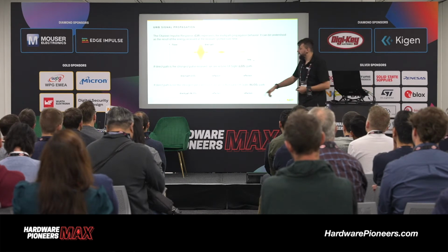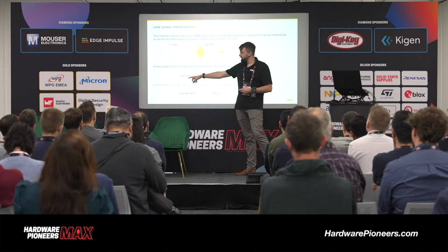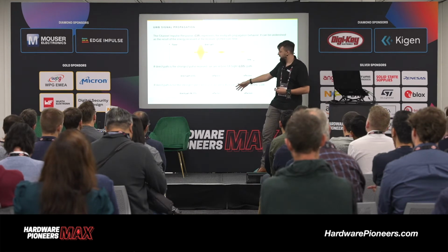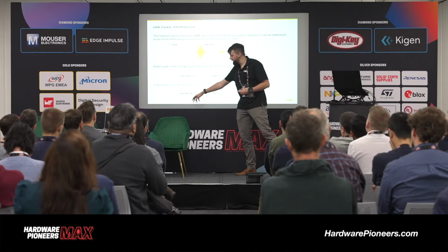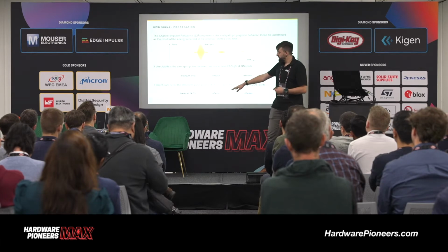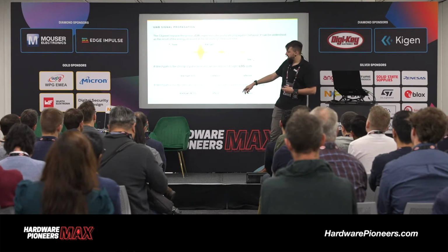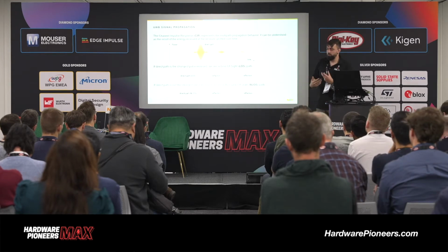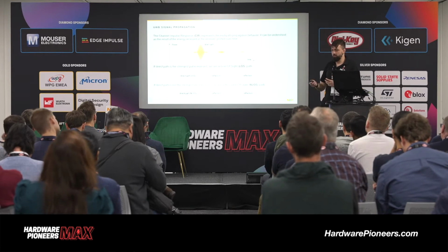You can see here, if we have a line of sight condition, the direct path is the strongest signal, and then reflections come in afterwards. In a non-line of sight condition, we have the direct path, which is not the strongest, but it's still received. And we have the first reflection, which is then the strongest, received a little bit afterwards. Our ultra wideband modules can discern between these two and give a moniker telling you if it's in a line of sight condition or not.